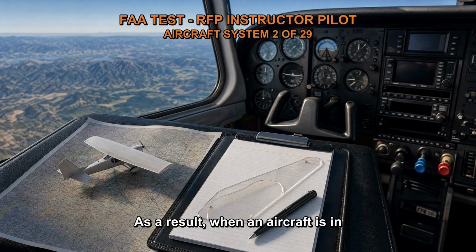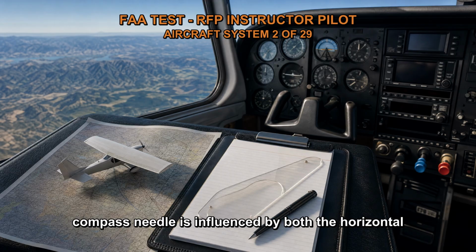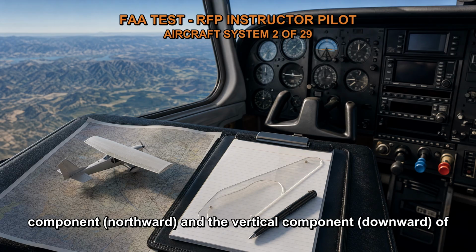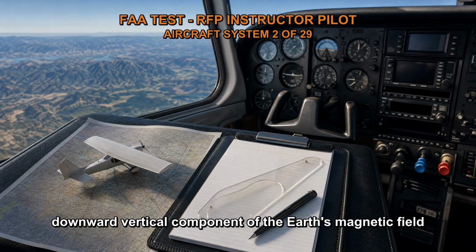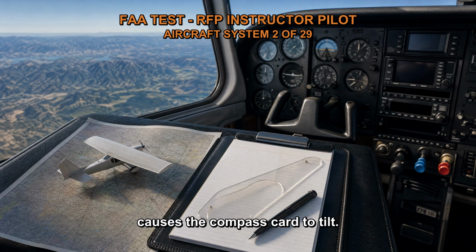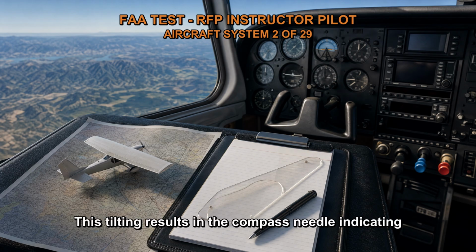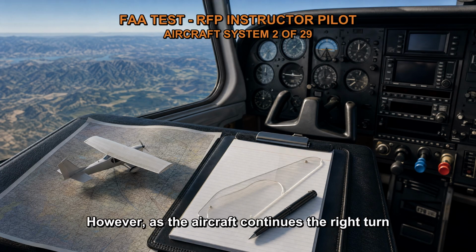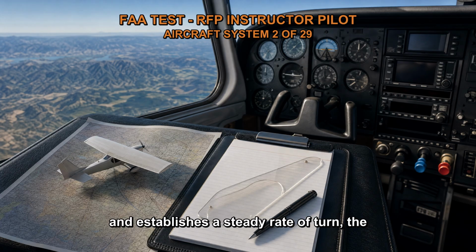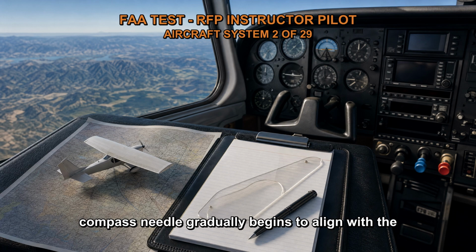As a result, when an aircraft is in a banked turn to the right, the magnetic compass needle is influenced by both the horizontal component, northward, and the vertical component, downward, of the Earth's magnetic field. During the initial phase of the turn, the downward vertical component of the Earth's magnetic field causes the compass card to tilt. This tilting results in the compass needle indicating a turn to the left, opposite to the actual direction of the turn. However, as the aircraft continues the right turn and establishes a steady rate of turn, the compass needle gradually begins to align with the new heading.